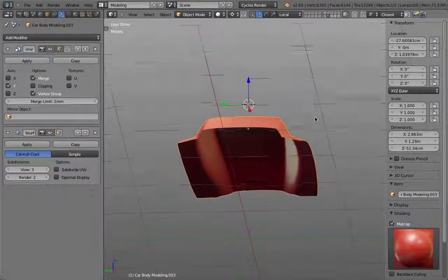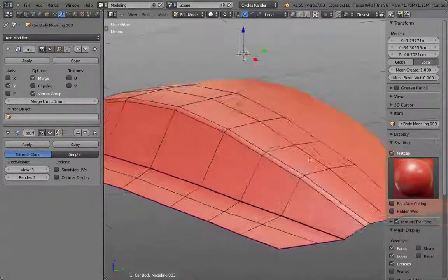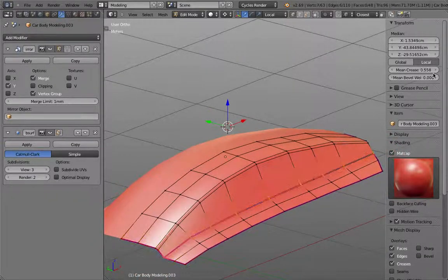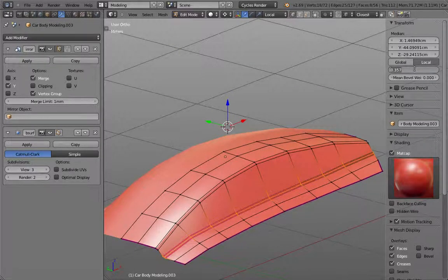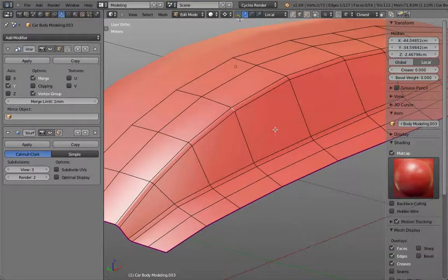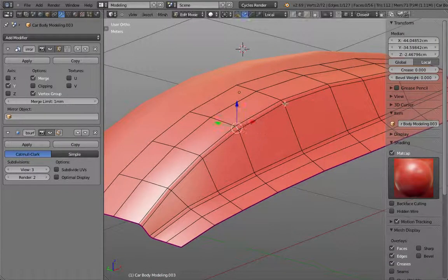So the fillet I basically put in is very uniform. Now if I want to make a nice transition, let's say I do the same here as well, I actually have to perform a little bit of scaling. So for example, let's assume here in the front those are fine. Then I can go ahead, for example, select this edge and then start scaling this up and scaling this up furthermore.